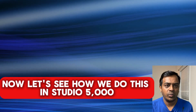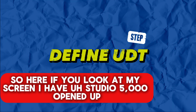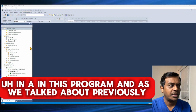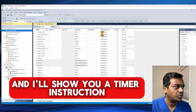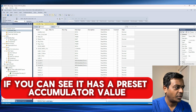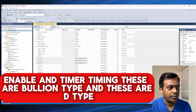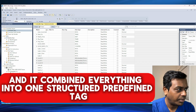Now, let's see how we do this in Studio 5000. So here, if you look at my screen, I have Studio 5000 opened up in this program. And as we talked about previously, we'll go to the controller tags and I'll show you a timer instruction. For example, this timer instruction has a preset, accumulator value, enable, and timer timing. These are Boolean type and these are DINT type, and it combined everything into one structured predefined tag.